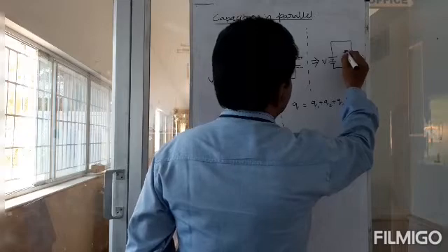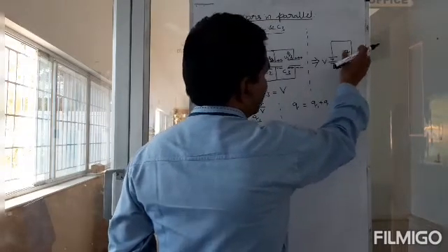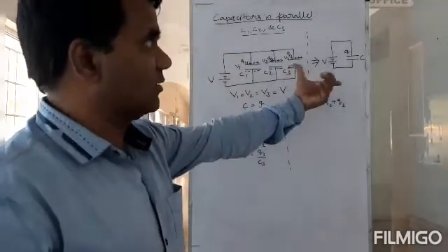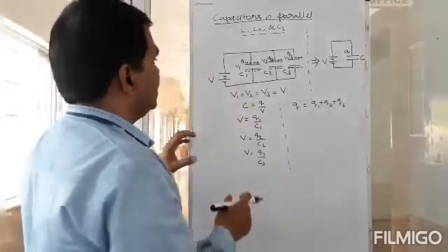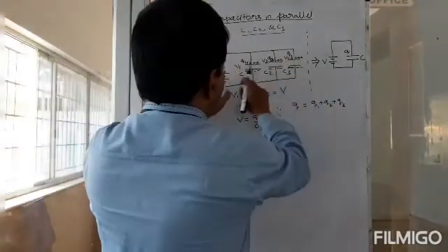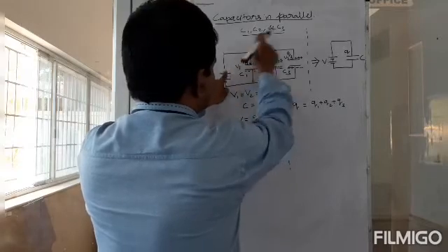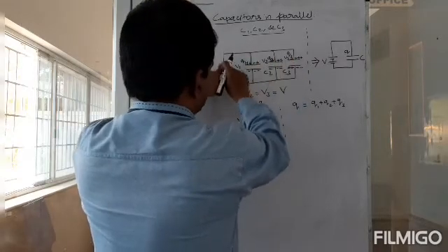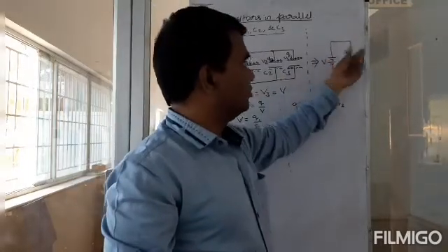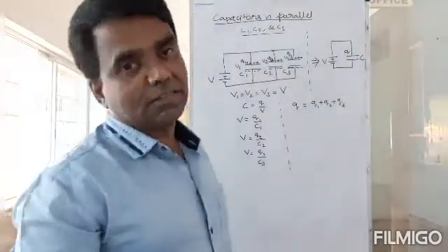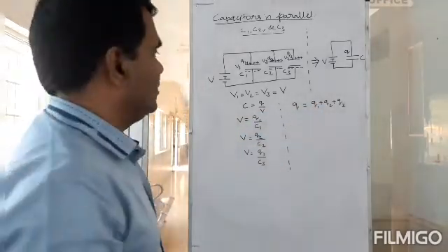So that is the charge we should have here. The battery would supply Q charge here. It will go and sit on that single capacitor, the effective capacitance. Because in reality, V supplies Q1 to this, Q2 to that, and Q3 to that. So V supplies Q1 plus Q2 plus Q3, and here also we will supply Q that will sit on a single capacitor. So that is the equation there.